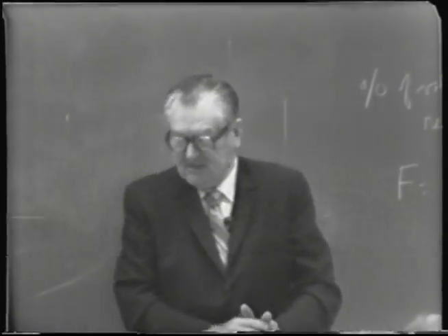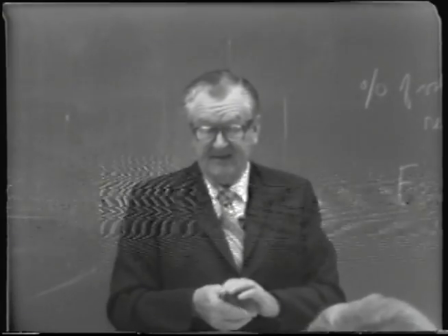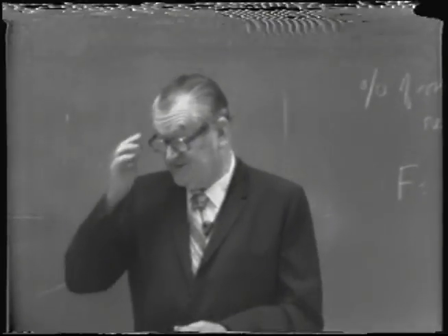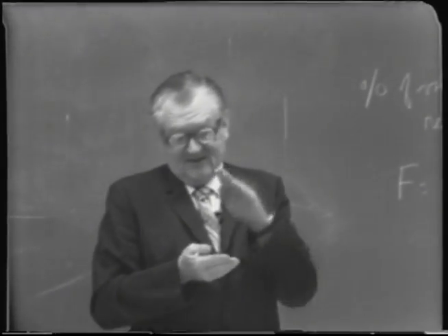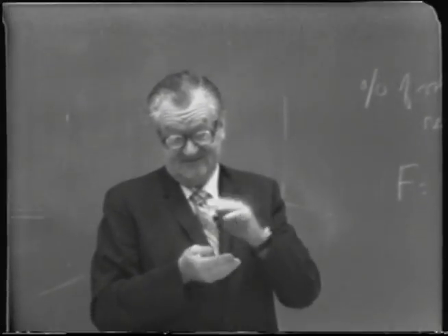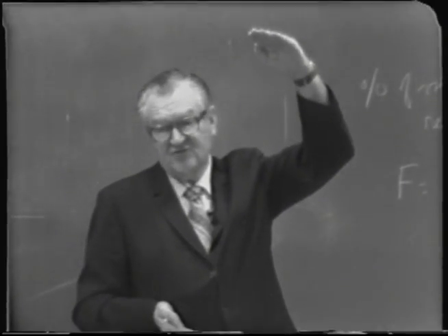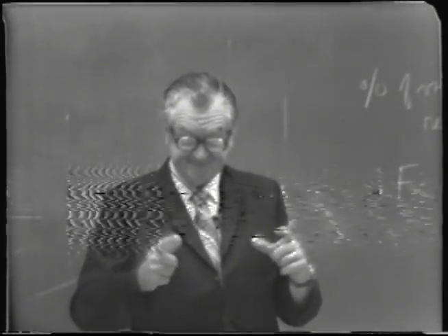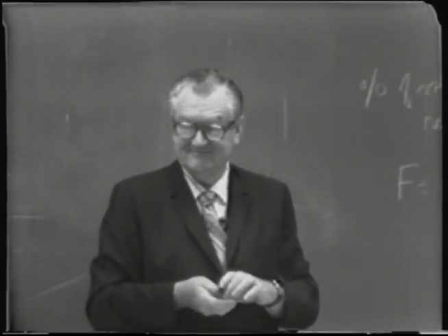Well, the height and diameter are sort of interrelated, along with plate spacing. Plate spacing determines the height, because, and we'll come to this later, by having larger plate spacings you can tolerate larger vapor velocities, and therefore have a lesser diameter for the same vapor velocity.